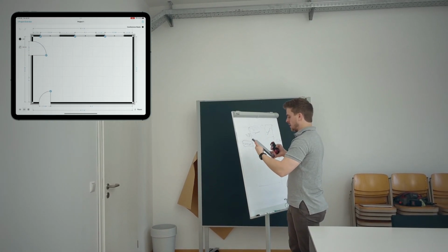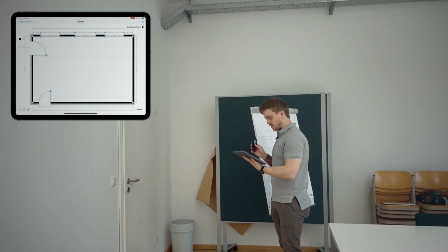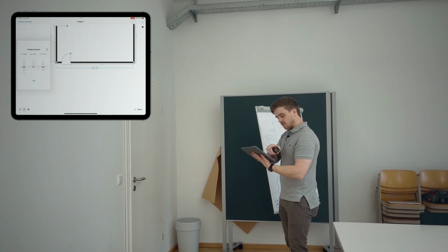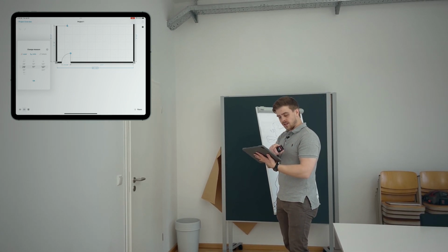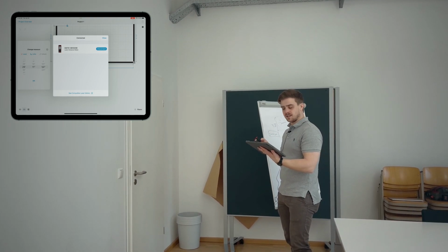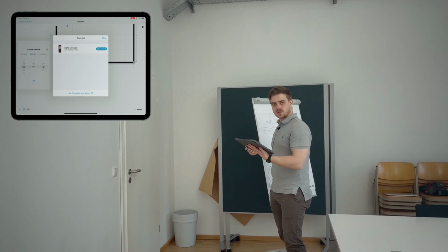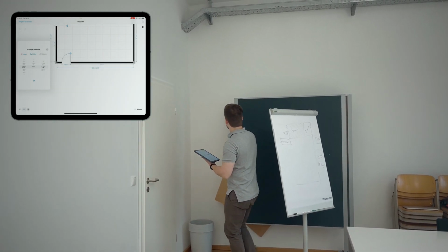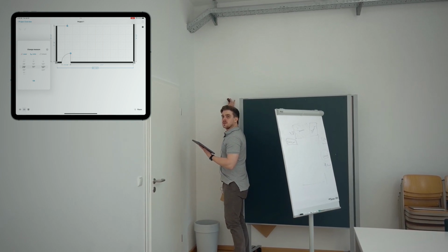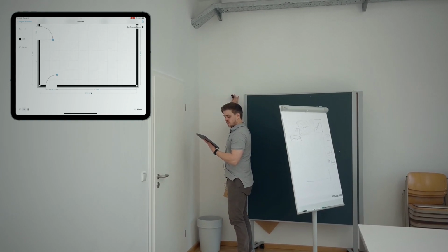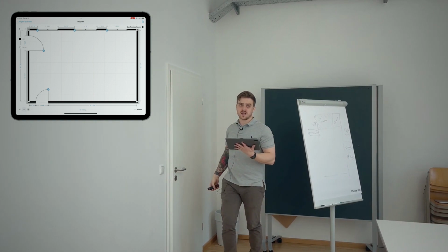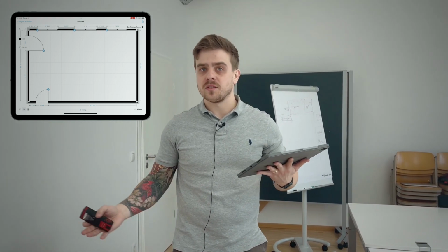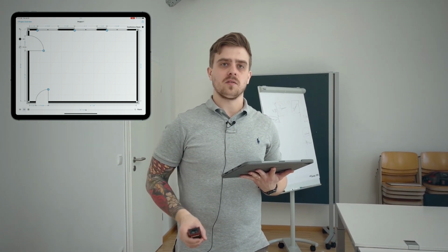Yes, I'm sure. And let's go ahead and make sure that this is connected. So I want to measure this wall right here. So I'll click on the dimensions down here, and you'll see my laser's already connected because there's the little red indicator next to laser. But if I hadn't connected yet, I would just click here and follow the instructions that you're prompted. So my laser's already turned on. So I'll stand right here, make sure I'm going across the room, and make small adjustments. As you can see, the LiDAR scan was really, really accurate, but this laser gives that 99 percentile accuracy that you'll need if you're an architect or a designer, somebody that needs that high level of precision.